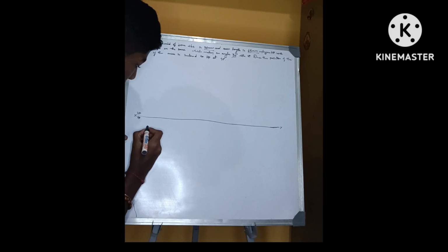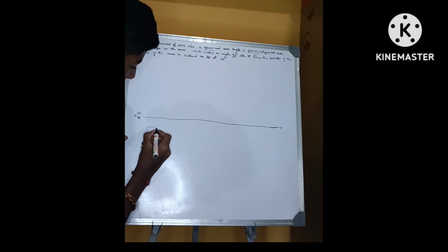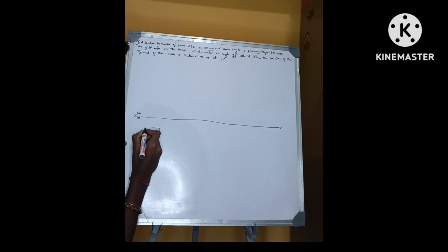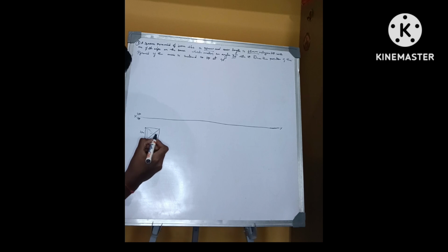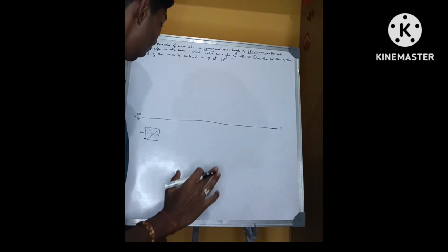Manually, take a scale and pencil and mark 35 mm from here, 35 mm from here, 35 mm from here, 35 mm from here, and give it the dimensions like this. Let it be 35 mm. No need to mention mm here; I have written it just for your reference. Then make the diagonals intersect like this, and let the intersection be O and let it be O1. Okay, this is done here.